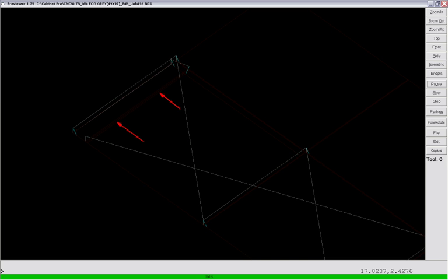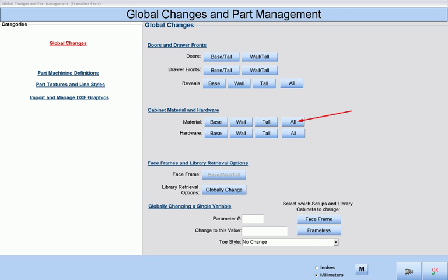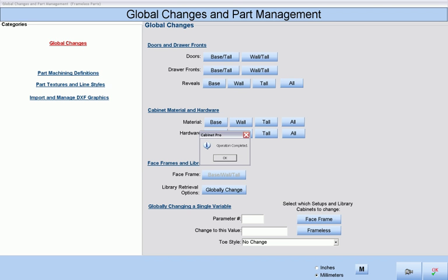And the 3/4 inch wide cut for the bottom dado is performed with 3 passes represented by 3 lines, since we were using the same tool with a 1/4 inch diameter. Now let's make a global change of material and change all of our material to a panel whose thickness is 1 inch. Changing all of our material to an extra thick panel will make our changes very obvious.